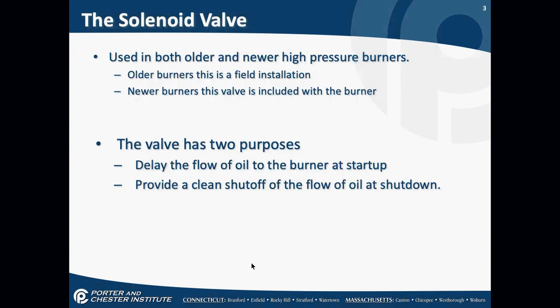The solenoid valves are used in both older and newer burners. Older burners, this is something we add afterwards. It's a field installation. Newer burners, this valve is included with the burner itself. It's part of the burner. It's either on the oil line or it's part of the pump. The valve has two purposes. It delays the flow of oil to the burner at startup, and it provides a clean shutoff to the flow of oil at shutdown.